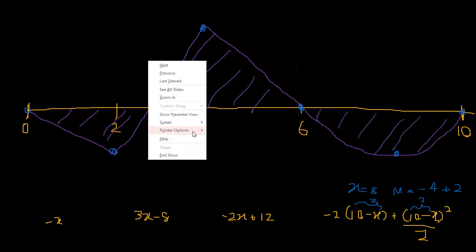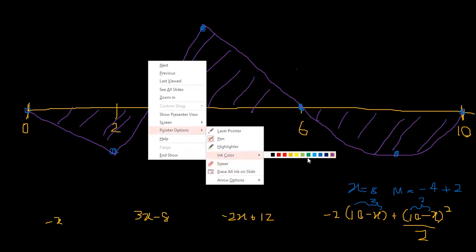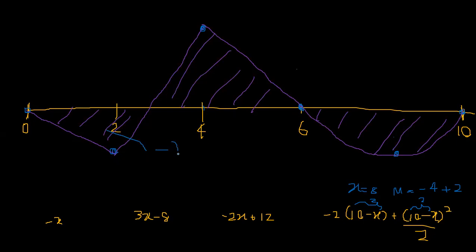So you can see, right? It's adhering to our fundamentals. Here it is negative, right? Bending moment diagram entirely negative. So what would that mean? It is sagging, right? About this part, we cannot say because a support is here, right?